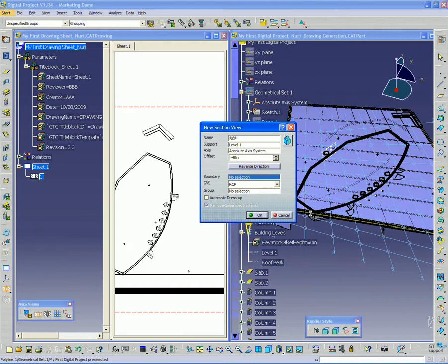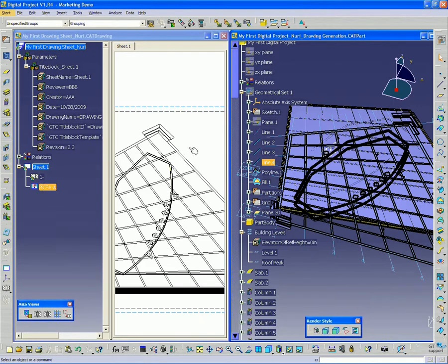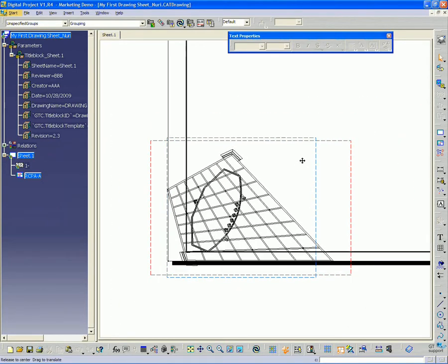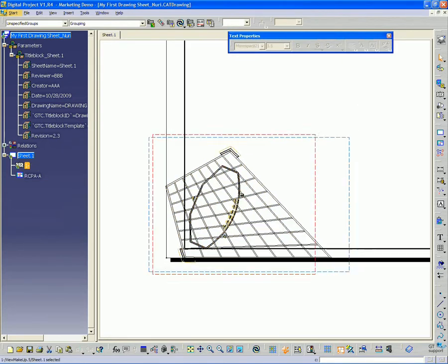And what it's basically doing is generating a plan looking up, but because it's going to be a mirrored view of the current plan we have, it needs to then take that drawing and mirror it, relocate the origin point so that this reflected ceiling plan lines up with our plan drawing. So now you should see in the 2D view that you have your plan view section cut and an RCP view cut.